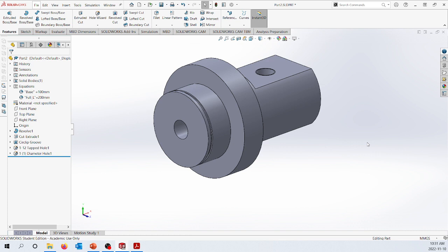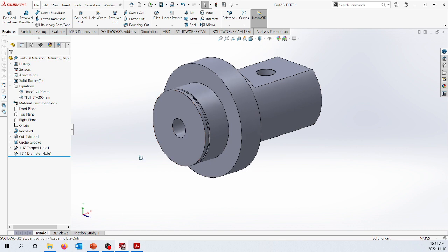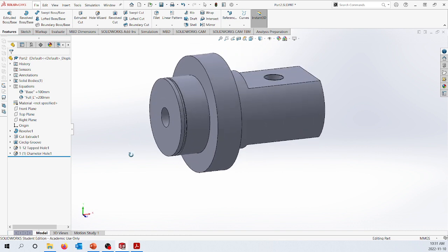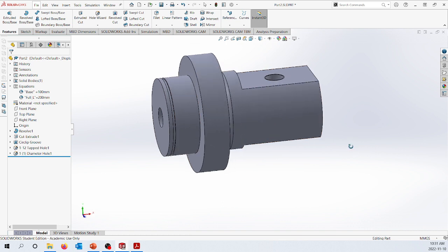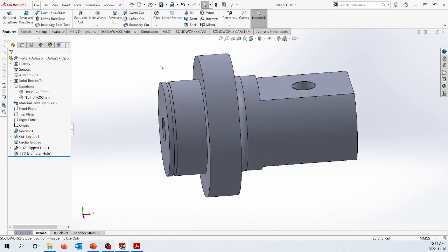With a couple of chamfers. So we like chamfers. We like to have them on our leading edges so they're easy to slide into locations so they don't slice our fingers open. And on this, we have chamfers on the ends, here and here, and on the inside, our leading edge of this hole. Now we might call this chamfer a countersink, but it's not even a full countersink. It's just taken off the edges. So we have some 2mm chamfers all over the place.